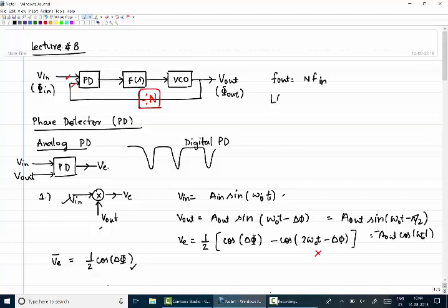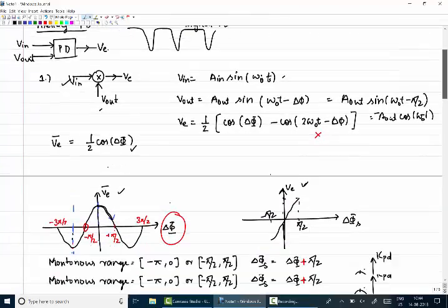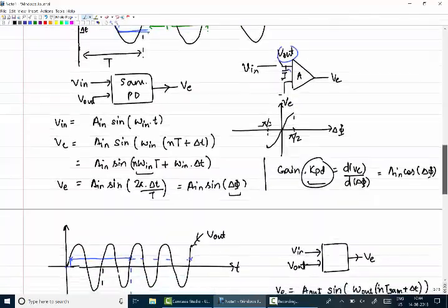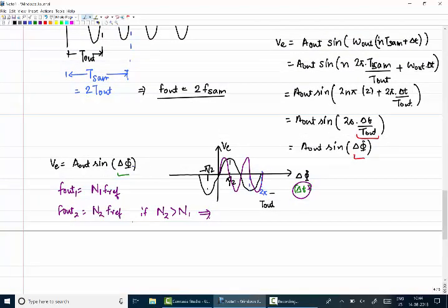Okay, and the loop gain of this PLL is going to be your KPD times F of S into 2 pi K VCO over S into 1 over n, because the phase also gets divided when the frequency gets divided. Now this is a conventional or typical PLL which we use. Now if I am using a subsampling PLL, a subsampler based phase error detector, where I am sampling the output frequency with the reference frequency, I do not need this divide by n.